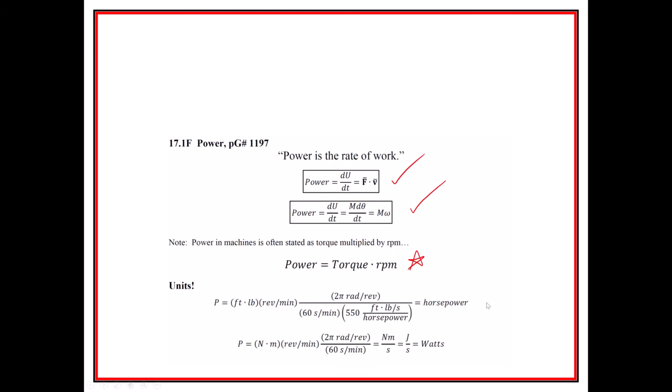And the same thing's true if you're a bicyclist, right? You only have so much power you're able to exert. But now, if you change the gears and you change the RPM of the output of the wheel, you will be running your pedals much faster, but you'll be able to get much more torque, and so you'll be able to overcome a much steeper grade. Right, so that you're able to apply torque into the output wheel.